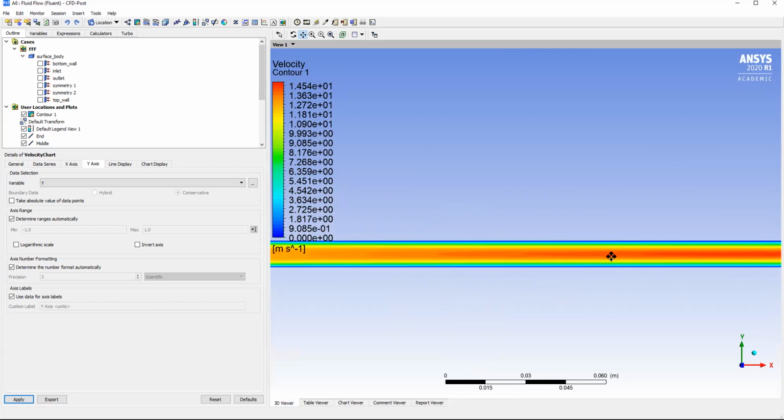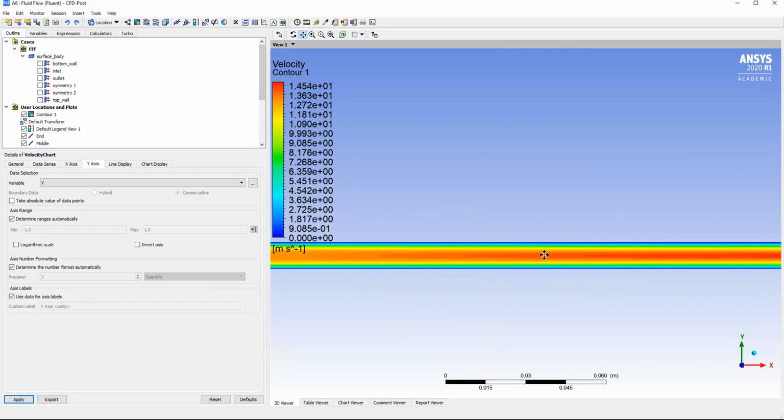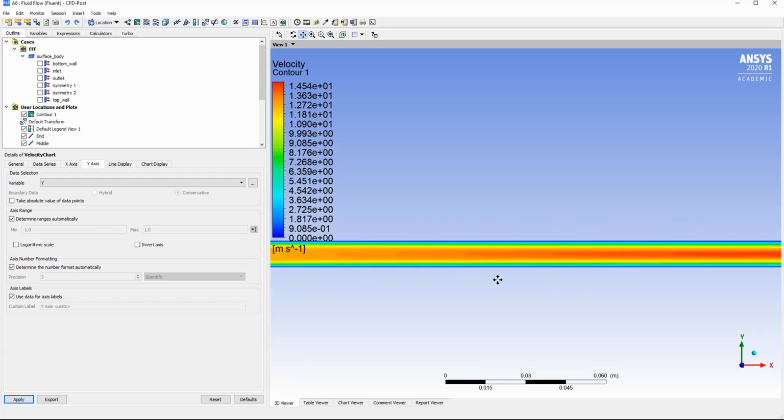And that can happen, let's say you have a machine part that you have lubricant, and you have 2 parts, 2 plates slapped on each other, and you lubricate the middle. The fluid flow of your lubricant will be a Couette flow because the top part of whatever machine we're talking about is moving, but the bottom is not. And I'll illustrate what that actually looks like to you right now.